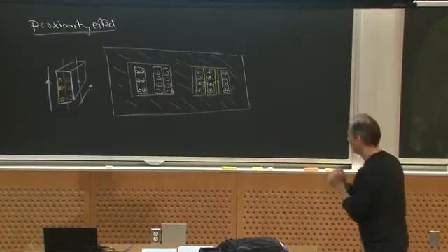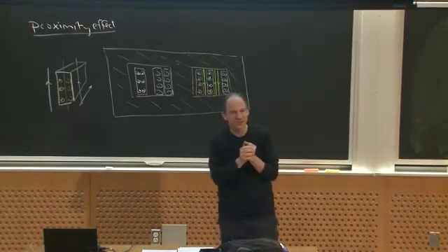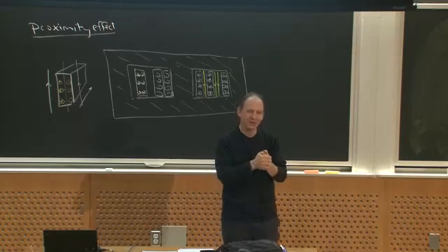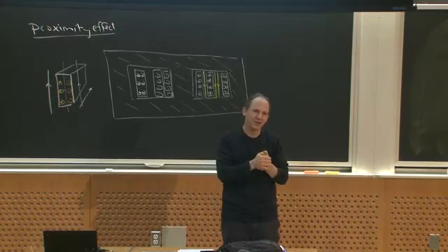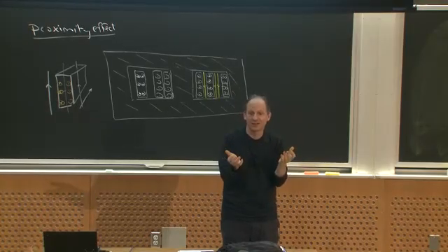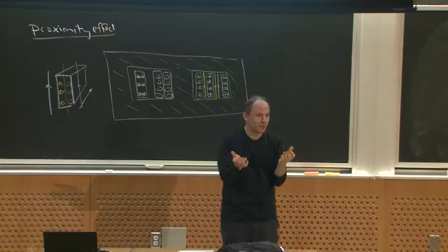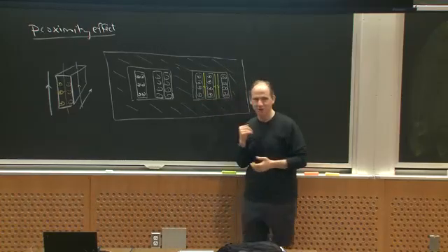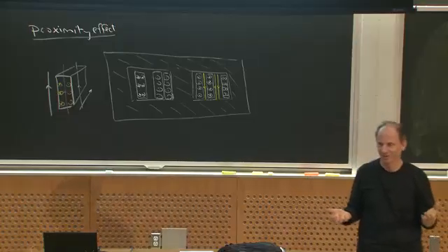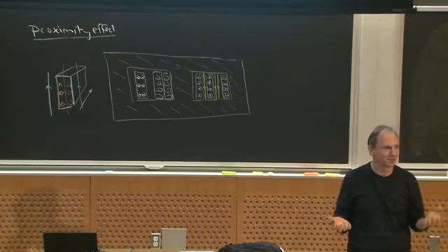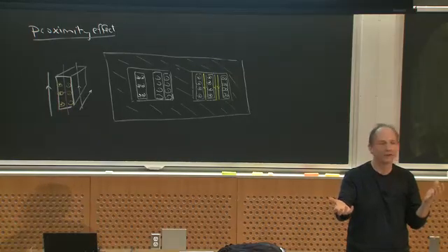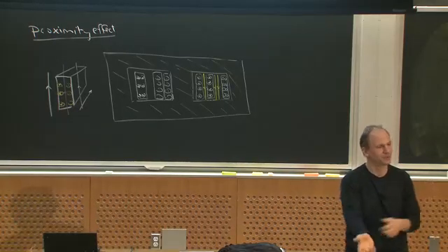So you could calculate your theoretical DC wire resistance, and say it's 10 milliohms. And then you could think, oh, but if I include skin effect, it's 20 or 30 milliohms because I have a bunch of skin effect. And then you figure out what the proximity effect is. If you have a bunch of layers, the loss can go as the square of the number of layers, so you could have 300 milliohms. Whereas your DC resistance might only have been 10 milliohms, suddenly you've got 300 milliohms. That's a factor of 30 times the loss you were expecting.